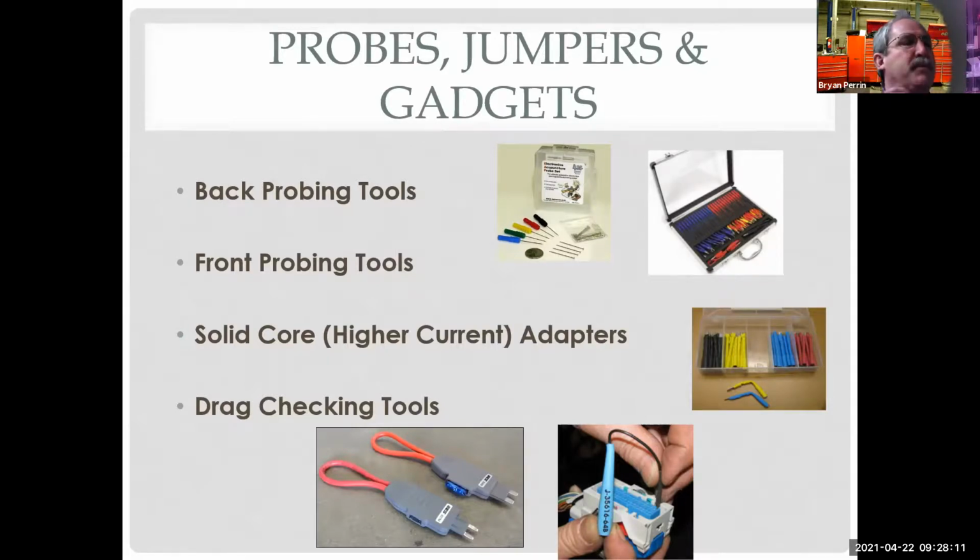As we get more expensive leads, we're going to have what are called banana plugs on each side. The banana plug is normally the plug that plugs into the meter, and the other side has banana plugs. Then I can put on a regular hand probe, an alligator clip, or these needle probes on the banana plug. These plug onto the banana plugs, and these are literally needles that go in. And this is nice because it comes with a spare set of needles.